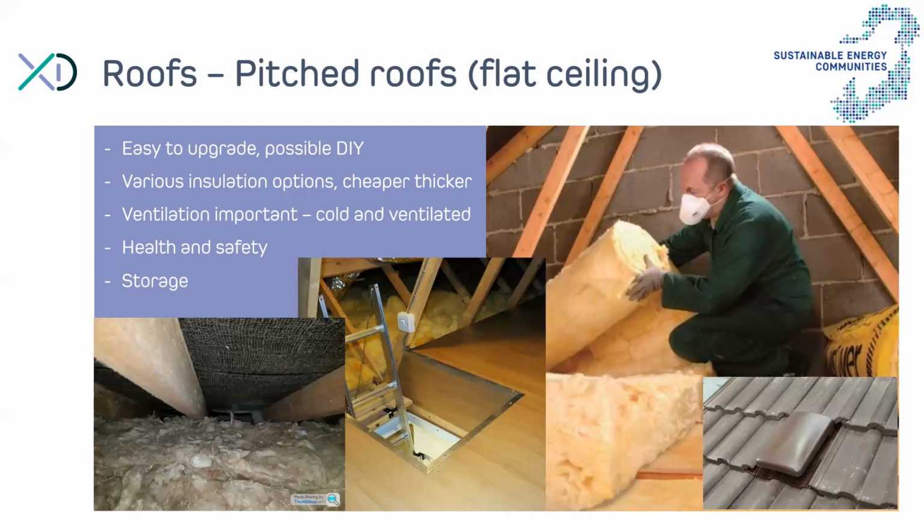A few other things to consider from a health and safety point of view is where there are electrical cables laid over the existing ceiling surface, typically quite loosely, and typically it's quite a mess. So certainly identify those heavy duty cables, those connected to an immersion heater or to an oven, for example, as they can overheat if they're pushed under the insulation. So they need to be lifted, maybe hung onto the joists in the attic, and then the insulation needs to go underneath to make sure there's no risk of fire.